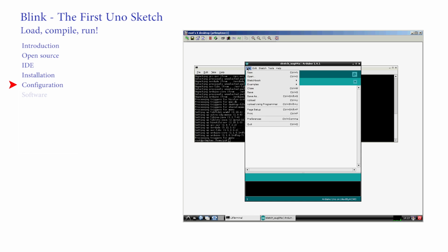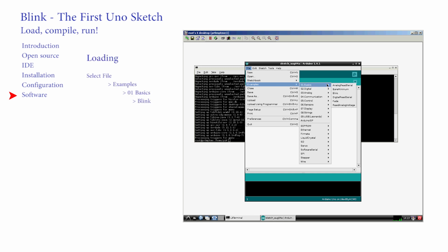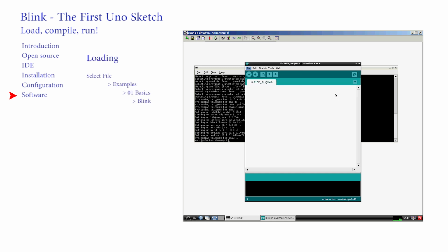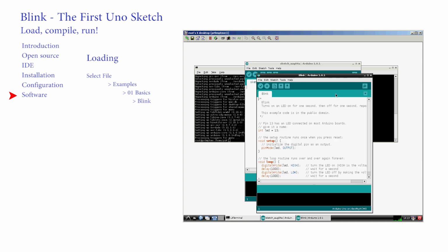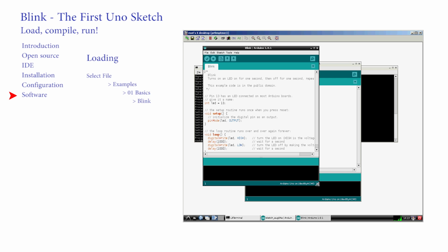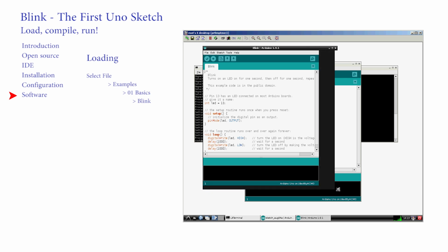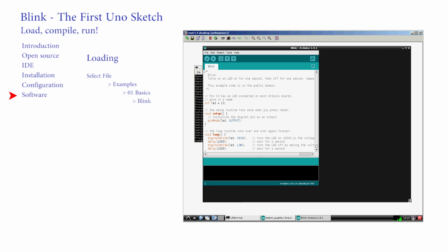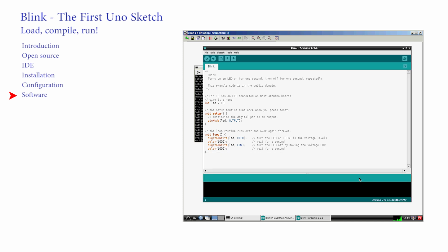With the hardware connections established, you can concentrate on software. Rather than write software at this stage, we can grab the first program by clicking on File, Examples, 01.Basics, Blink. Printing Hello World is typically the first program that is run in any software course, but with the Arduino, it's the Blink sketch. The program should appear in the text box and we will examine it later.